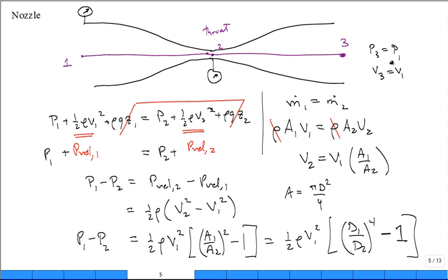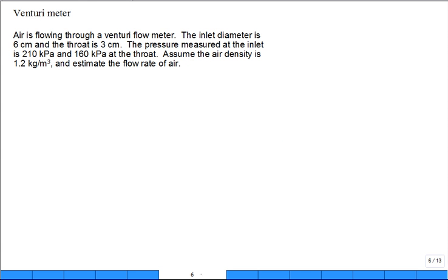So what happens is the nozzle is pretty easy to make and have a good efficiency, but the diffuser is a lot harder, because in reality when you try to have it opening up, the flow will sometimes want to slip around and get into little recirculation patterns right in there. So you have to be very gradual on the diffuser opening up. The nozzle you can neck down pretty fast, and it'll follow the flow. When you combine a nozzle with the diffuser, just trying to recuperate back up and not lose any of that mechanical energy of the fluid, what you have is a Venturi. A Venturi meter.